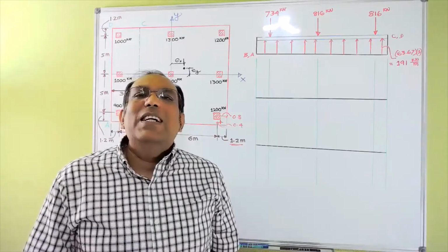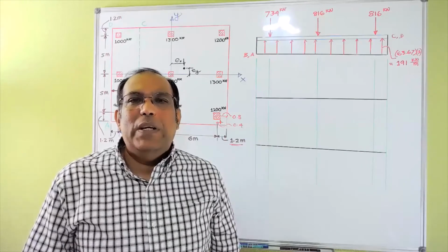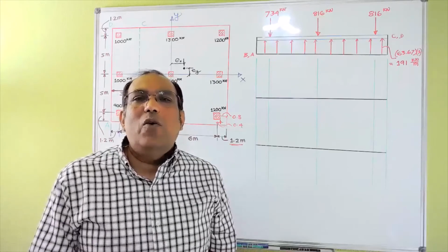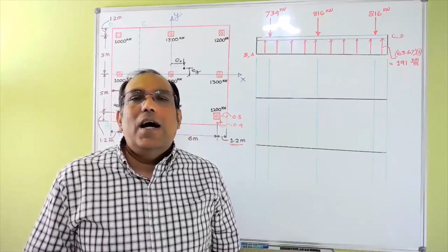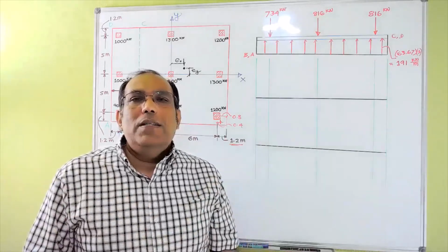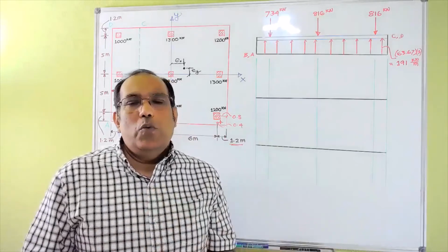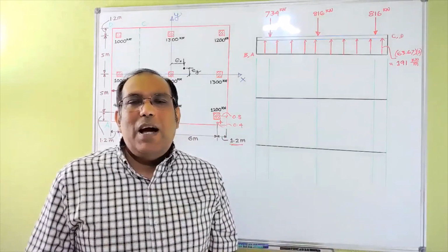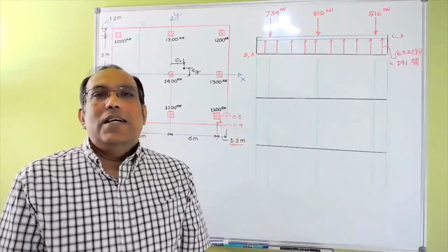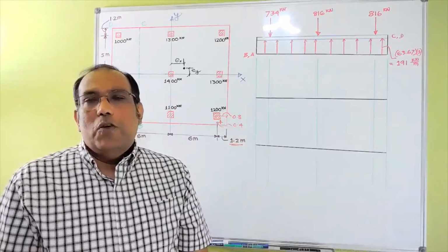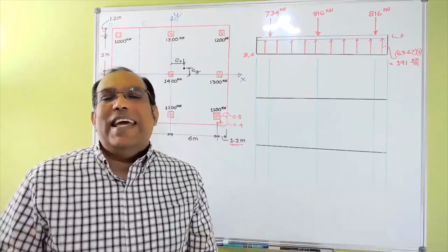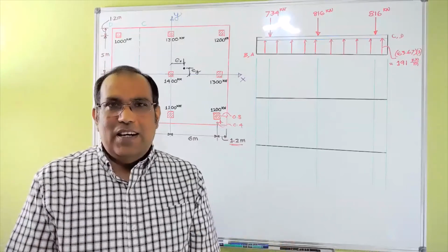I know you already learned how to draw the shear force and bending moment diagram, but in foundation engineering, how we adjust that soil reaction as well as the load coming from the top, that's basically what I wanted to show you. But now you see that after adjustment, the summation of forces in the y direction is 0. So basically, if you draw the shear force and bending moment diagram, they are going to close at the end. Okay, this is the most important thing here.